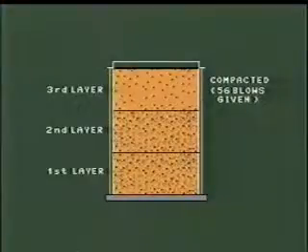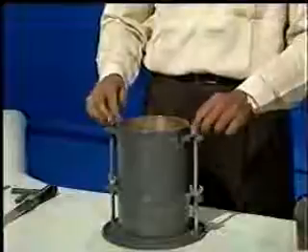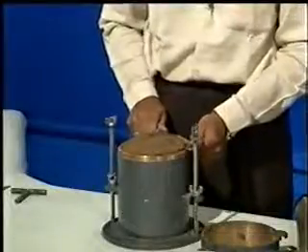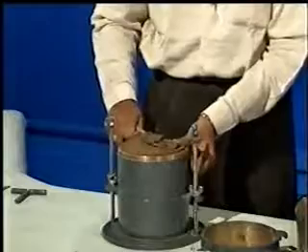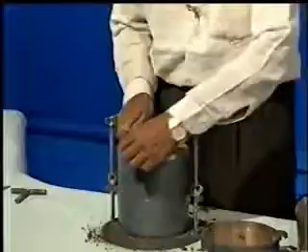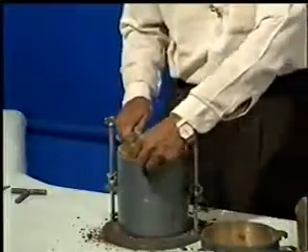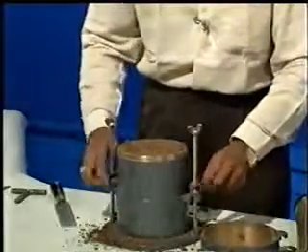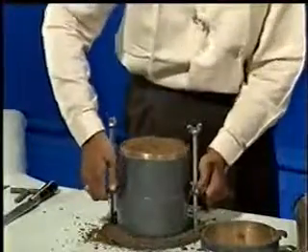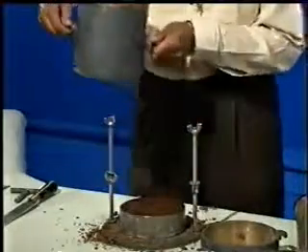After compacting the top layer, remove the collar and trim off the top surface. Also remove the base plate.